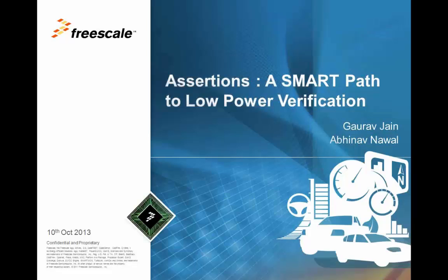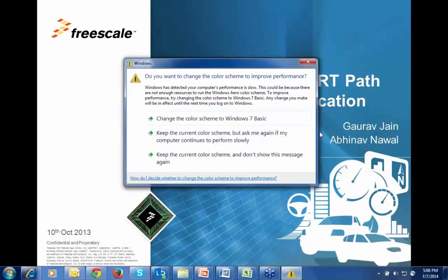To achieve this, designers are using techniques like power shutoff, dynamic frequency and voltage scaling, well biasing, etc. to ensure that the device operates within the power budget limits of each mode. This has significantly increased the verification complexity, with a new paradigm of low power operation added to the normal functional verification and the need to check the device behavior in each mode.